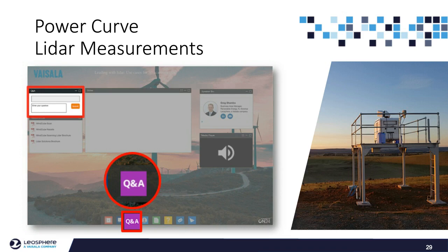How long does it take to gather enough information from the scanning LiDAR and the nacelle-mounted LiDAR to perform a power curve test? Well, that would depend on the, well, in this case, we're doing tests for several weeks, but I mean, the scanning LiDAR, you can program so that the scan itself could last a few seconds or a few minutes. So you can already compare the data on a one-day basis if it is needed. And most of the time they use average data, so it might be 10-minute average data, and that can be possible as well with both instruments. Okay.